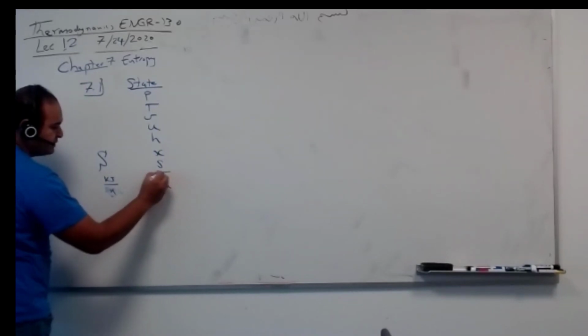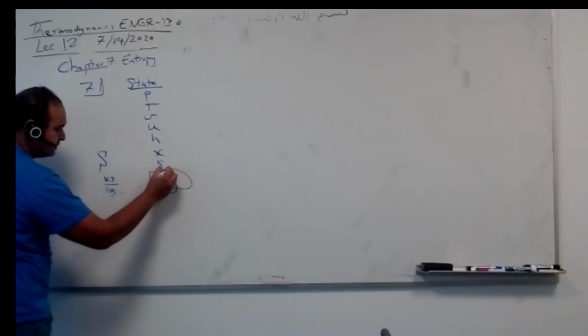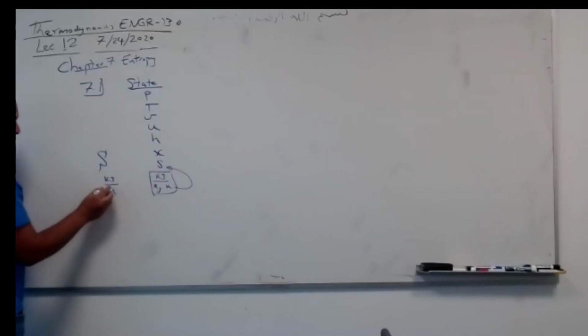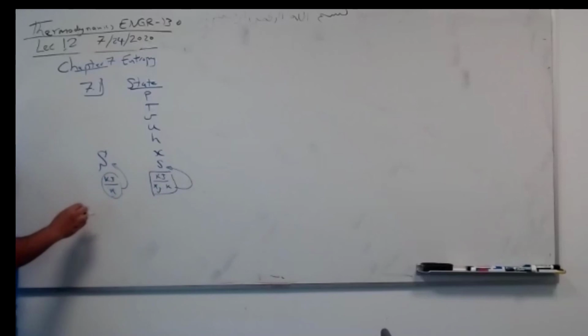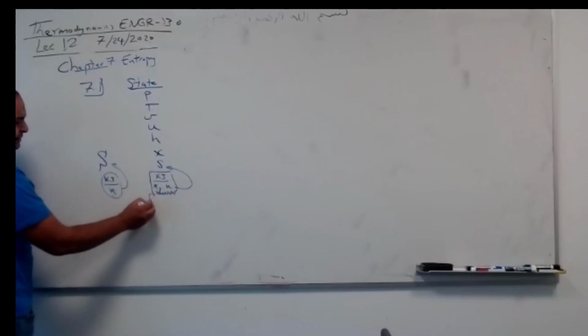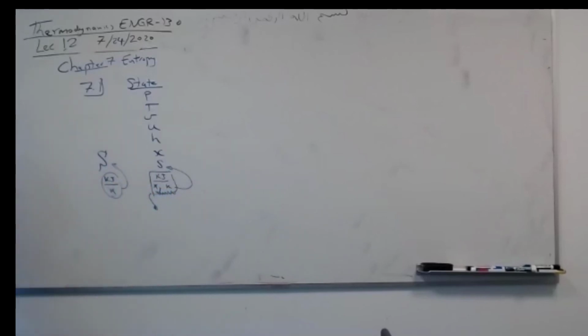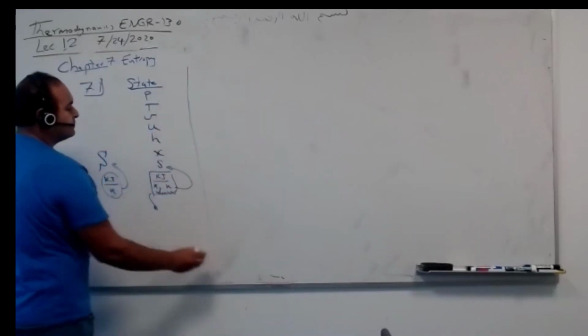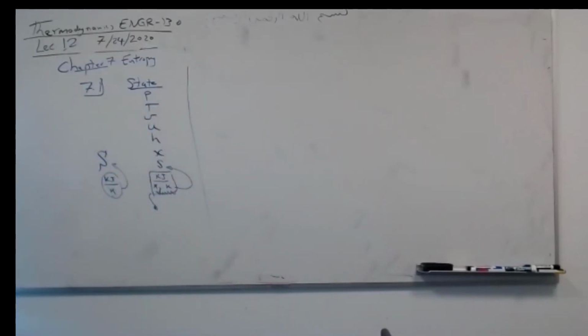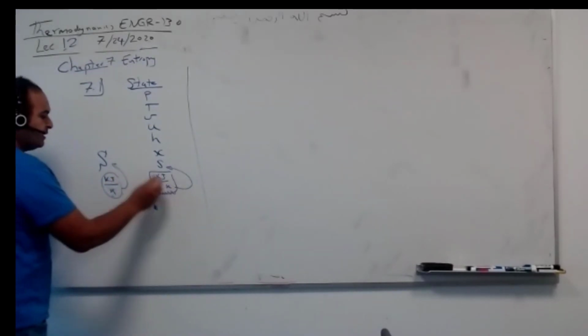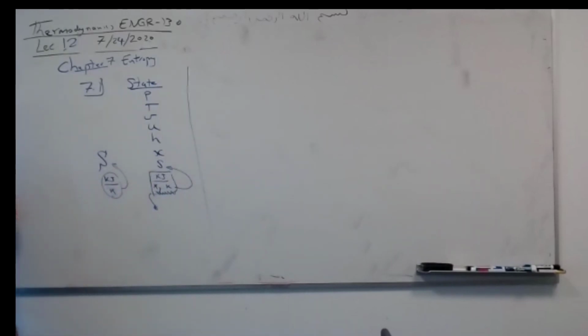Do you know where you saw this unit before? Does anyone know? This is entropy, this is specific entropy. Where did you see this, guys? Can somebody tell me? Specific heat? Exactly. It's similar to specific heat in units. It's heat per unit mass, per unit temperature, but it's not exactly a specific heat. It's similar in the units, even similar in the equations, but not similar in terms of definition.